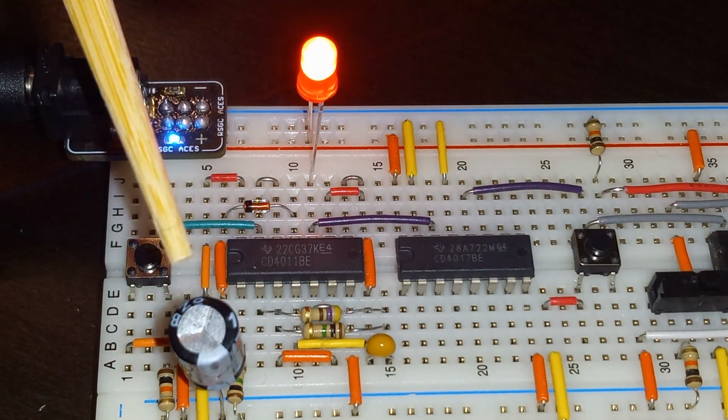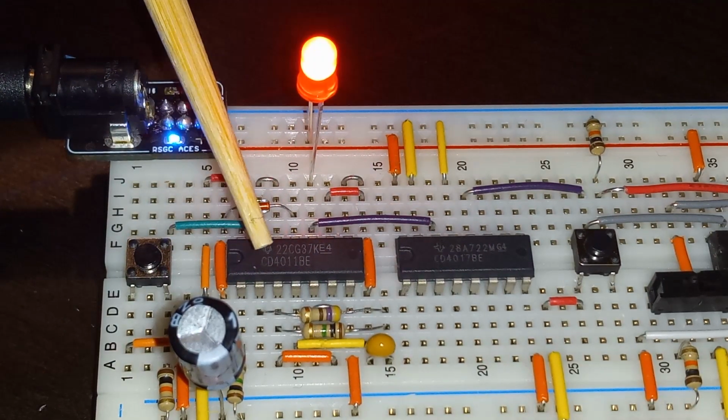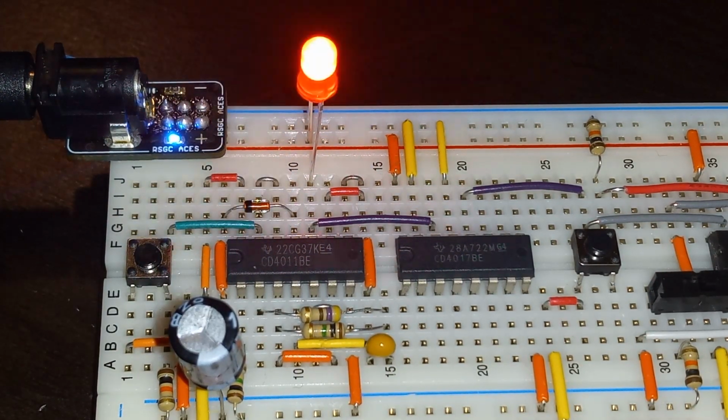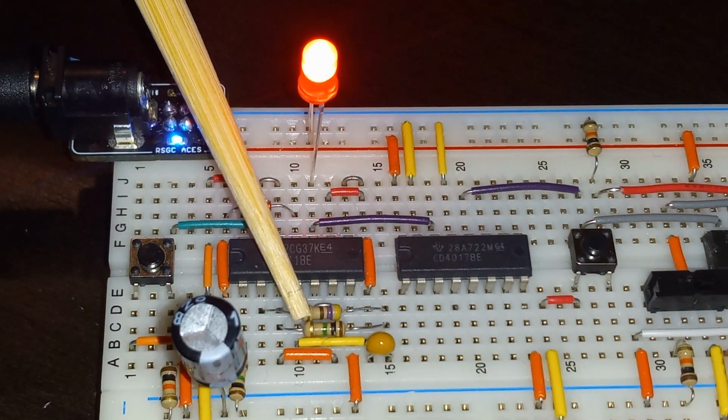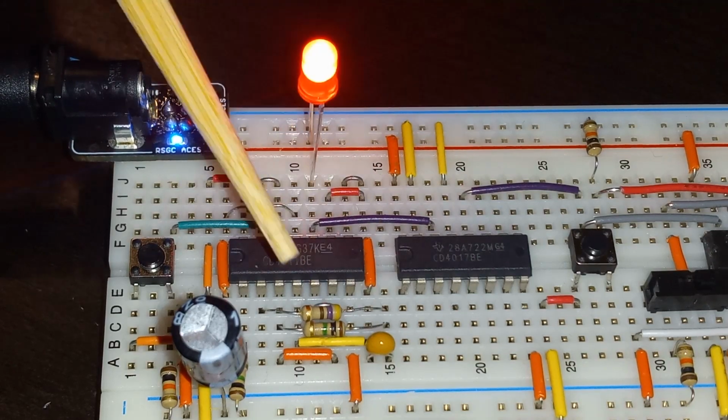As the capacitor slowly discharges, one input lead of the second NAND gate will be high. Because the other input is low, the output is high. This high goes through the 1 megohm fixed resistor to the 0.1 microfarad capacitor. These components can be referred to as RC2.